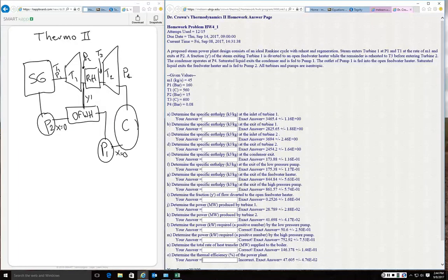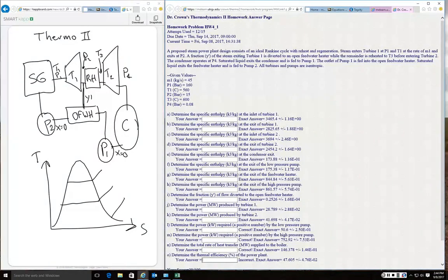Let's next do a T-S diagram. And we have P1, P2, and P4. Those are our 3 pressures. Even though I skipped state 3, that's not another pressure. State 4 is at the same pressure as state 2. So I've got P1 at the highest pressure, P2 the next pressure, and P4 is the third pressure we encounter. And then coming back through the pumps, pump 1 we go from pressure 4 to pressure 2, and then pump 2, pressure 2 to pressure 1 again.